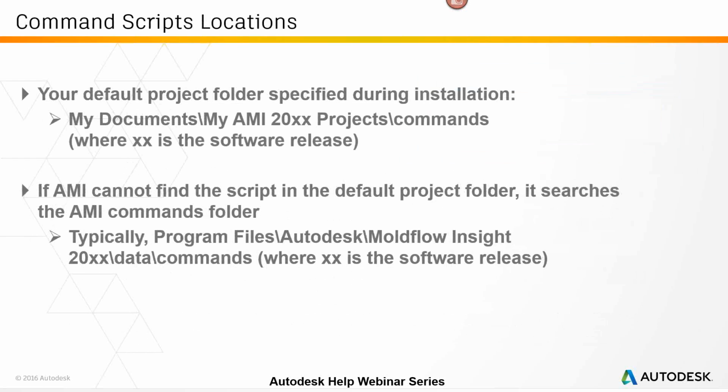So scripts are in the scripts folder, and commands are in the commands folder. So again, the same projects directory that we talked about before, but rather than scripts, it's under the commands folder. If it can't find the script or command that you have typed in, it'll look first for your local folder, being this folder, and then it will go to the default folder, which is where all those commands are located. So again, the hierarchy is it looks locally first, and then to your main commands, which are located in the default installation directory.